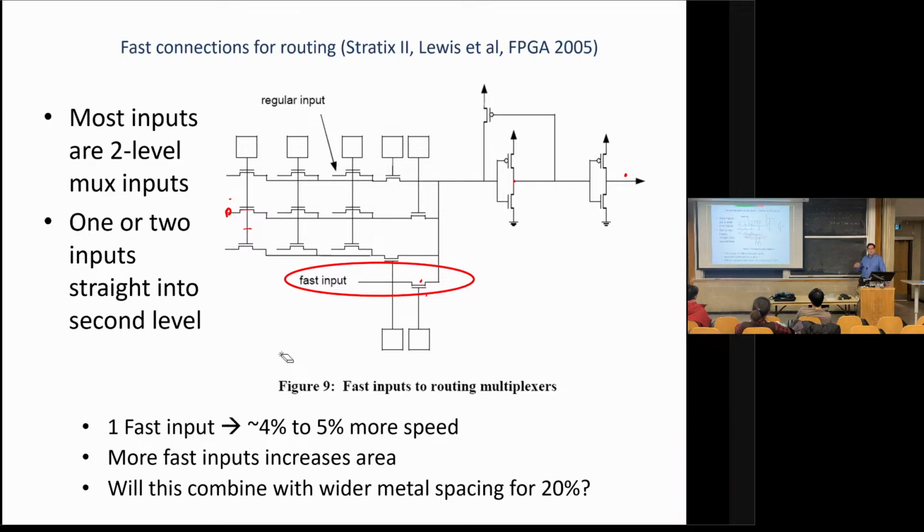The router's pretty good at finding the critical paths and putting them on the fastest resource. But if you start making all sorts of constraints, well, this one's a bit faster this way, this one's a bit faster that way, eventually the router just can't handle all those constraints. With a lot of unbalancing, it can get so difficult for the router to line everything up that it still works, but you don't get quite as much gain as you hoped for.